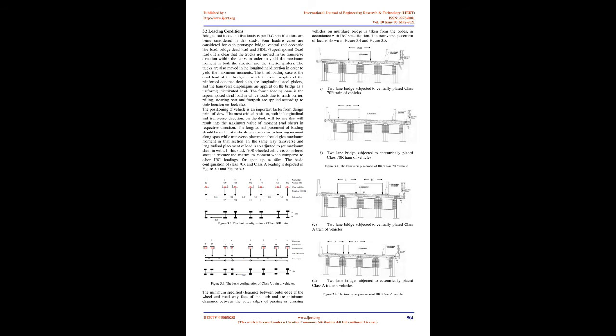Live load reaction at support and shear at the beam ends of the selected bridges were determined using finite element analysis. The comparison of the distribution factors of live load reactions and shear revealed that the distribution factor of reaction at piers was higher than that of shear at beam ends near the same support. The increase in the reaction distribution factor was more significant than that in the shear distribution factor in the interior beam line when the skew angle was greater than 30 degrees.